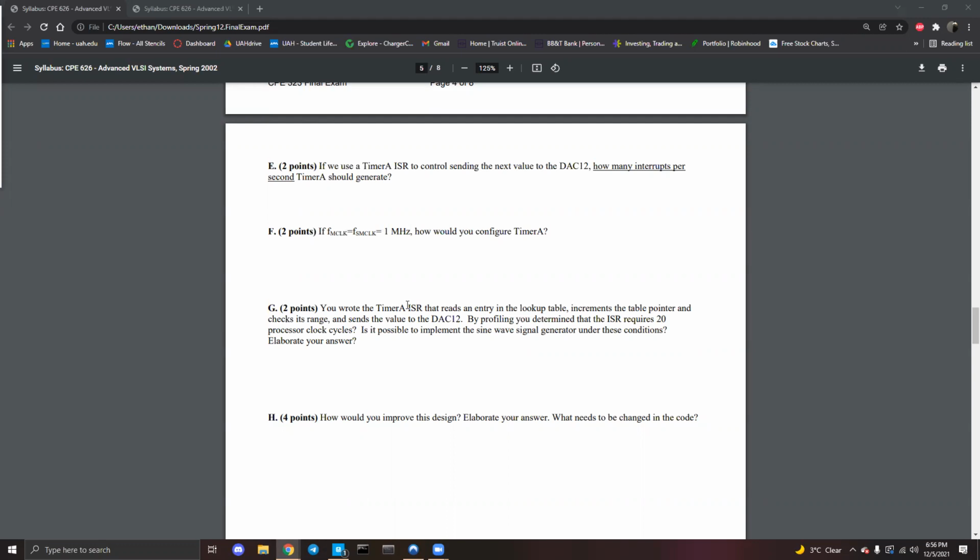I don't do it because it's not necessary. It won't make enough of a difference. You'll be off by like 0.001 hertz, and it really doesn't matter. My frequency was 49.99 hertz. I had no necessity there. All right, but that's all it is. The value here, 1 megahertz divided by 20,000, and then subtract 1 from that quantity is 49. So that's just the number you shove into the TACCR0 register for timer A. Make sure you know it's CCR0. If you don't have a CCR0 value, nothing's happening with your timer.